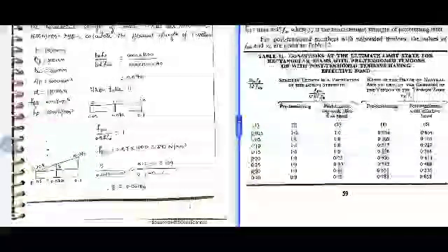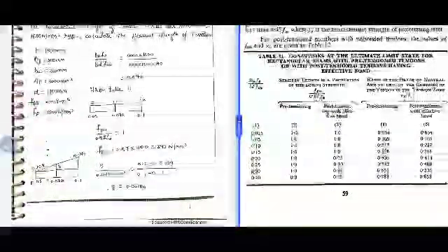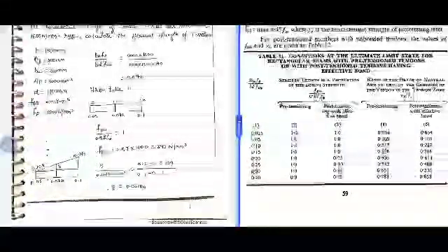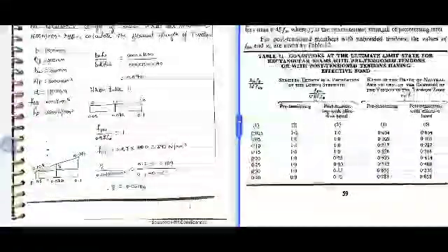So on the right side you can observe on the screen, here effective reinforcement ratio is 0.074. So it lies between 0.05 and 0.1. For both we have 1, it is bonded flanged section, remember that.